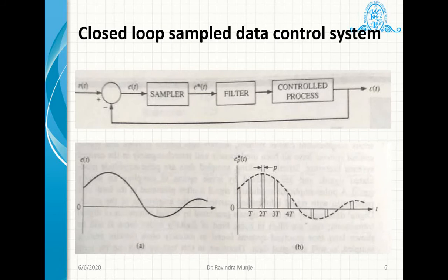So a digital control system has a digital transducer. They are often in some kind of digitally coded form, right? So that is a digital control system. And discrete data control system describes all systems having some form of digital or sampled system. So when we say discrete data system, it includes both sampled data signals and digital signals.